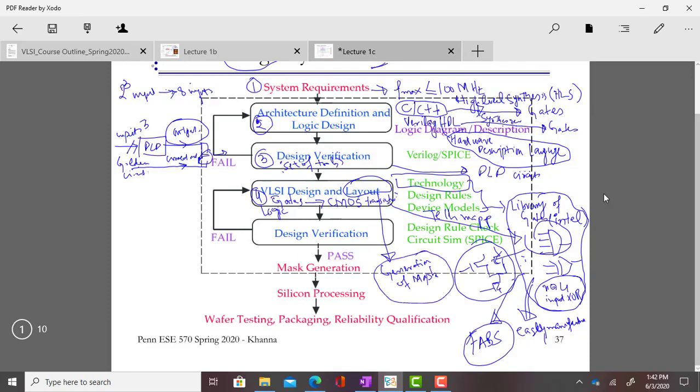So in the last part I told you that chips are manufactured using a mask, and this mask is exposed to light. So we throw light upon this mask, and the circuit on the mask is transferred to the silicon below the mask.